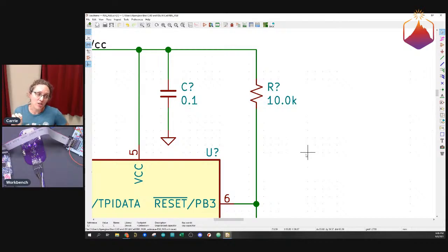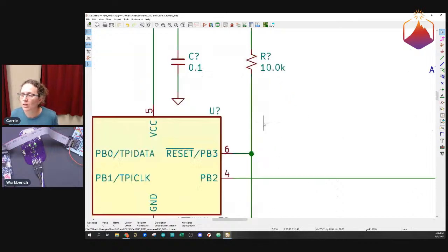The ATtiny5 also has 512 bytes, but it has an extra feature, an A to D converter, which means it can read an analog voltage, a voltage that varies between 0 and 5 volts. The ATtiny9 has 1024 bytes, and so does the ATtiny10. Again, the difference is whether they do or do not have an A to D converter. So yes, thank you. Good info.